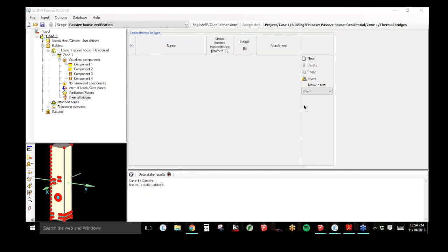When designing a multifamily or apartment building, does each apartment need to be drawn and assigned as a new zone? No. I was trying to illustrate that there with the beach green. Typically, you just need to look at a couple worst case conditions. So you pick what you think might be the worst case for the heating. So what's the coldest unit? Least amount of solar gain and most amount of transmission losses. So what's the most exposed? And then also a worst case cooling condition, which I showed was that southwest. So it had the most amount of glass, and it also had direct exposure to the roof on the top. So you should look at the worst case conditions, try to optimize those, and then by doing that, inherently you should be okay with those in between cases.